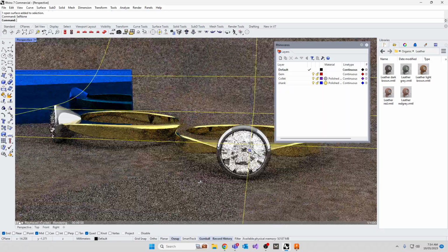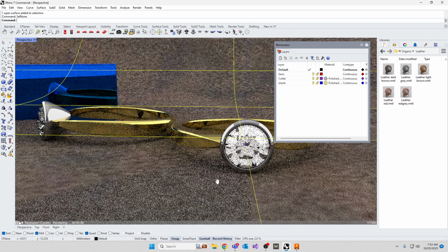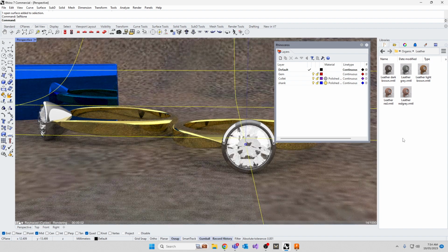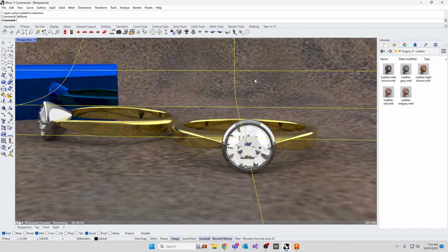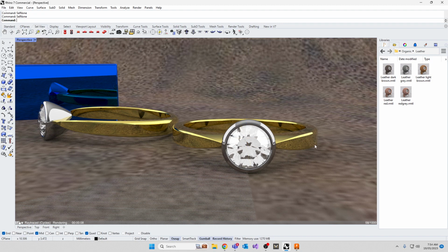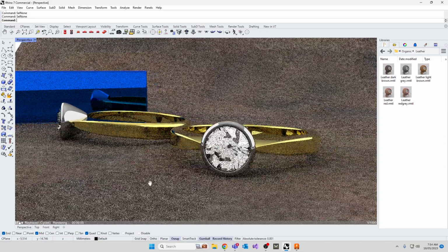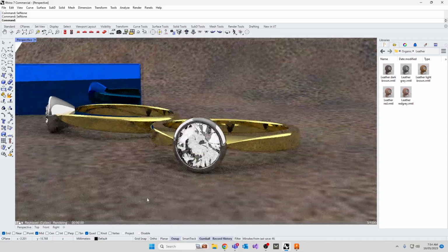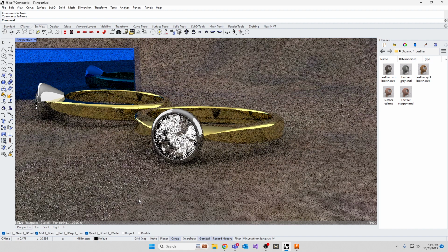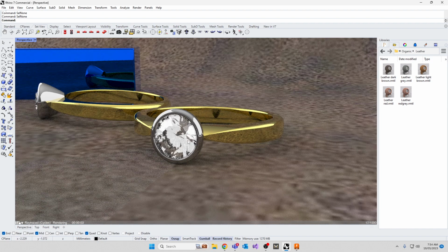So the other nice thing with doing a render, I'm sorry that this is getting a bit complicated, but you want to change your camera focal point. All right, so I'm going to go select none again. We want to focus on this, but we want the stuff in the background to be a little bit out of focus, because with a real camera that's what happens. So we want this area to be in focus, set up our plane there, but everything else not.